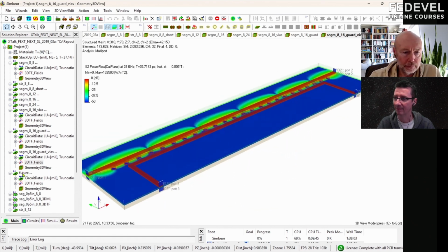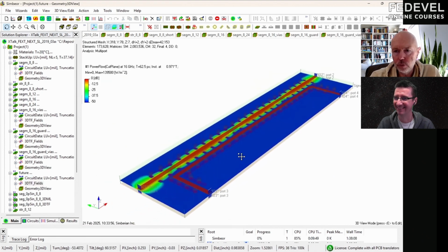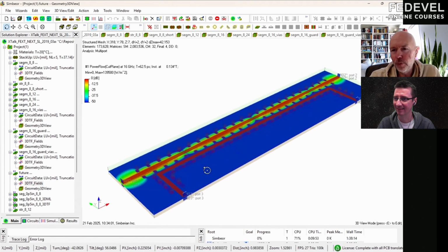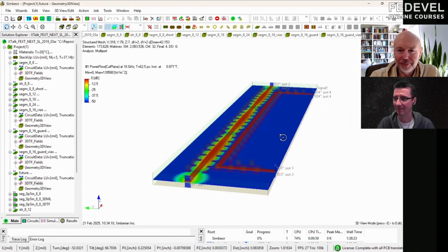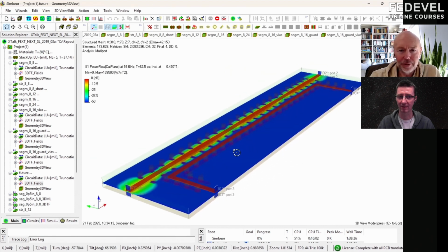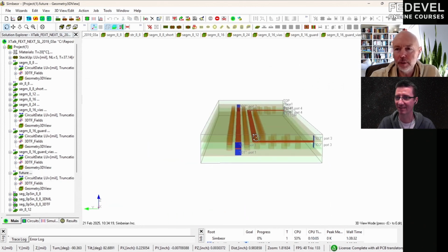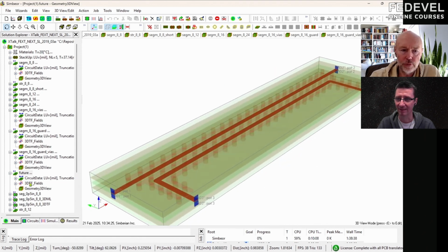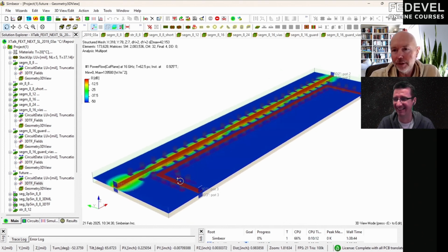Well, if you go to extreme, I bet all boards are going to look like this pretty soon. This conquest of 448 gigabit per second that we saw at DesignCon will require boards that look like this. So ground traces on both sides and many vias, essentially a coplanar structure, coplanar routing with a lot of stitching vias, like a waveguide. Exactly. Yes, it's a waveguide.